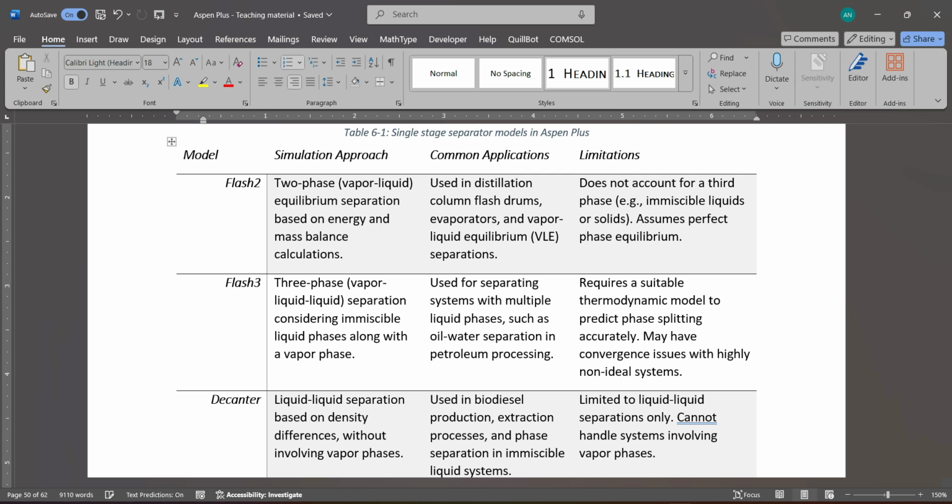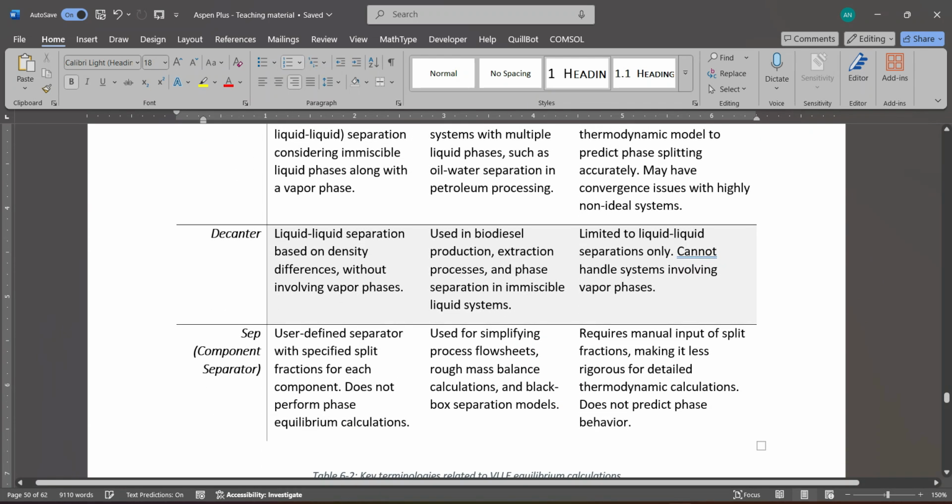There is another theoretical block in Aspen Plus with the name SEP, that is a component separator block. This is purely a theoretical or user defined separator where the user can define specified separate fraction of each component in the streams. It does not require any physical background. However, it serves the purpose when any of the other available separation blocks are not suitable for the application, such as the membrane separation, or the explicit details of the separation philosophy is not of interest.